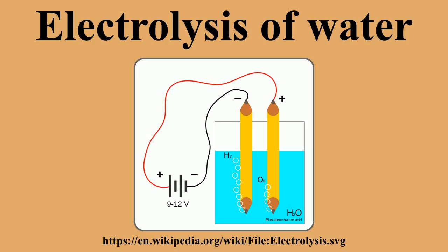High-pressure electrolysis is the electrolysis of water with a compressed hydrogen output around 120 to 200 bar. By pressurizing the hydrogen in the electrolyzer, the need for an external hydrogen compressor is eliminated. The average energy consumption for internal compression is around 3%.